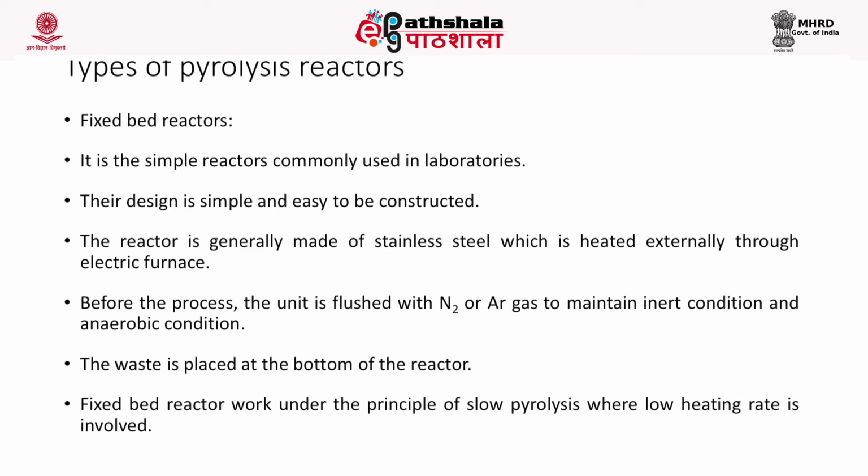Before the process, the unit has to be flushed with nitrogen or argon to maintain an inert or oxygen-free condition, because pyrolysis is done in the absence of oxygen. Now, the waste will be placed inside the reactor at the bottom, and generally the fixed bed reactor will work on the principle of slow pyrolysis, where the heating rate will be very low.